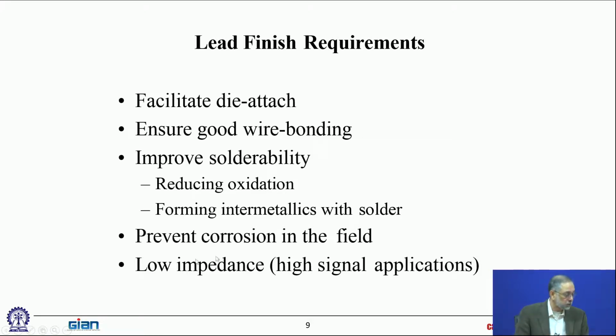And then again, not every pad will be soldered. The remaining will just have the lead finish on it. So that's supposed to also prevent corrosion in the field. So you pick the finish material based on that. And sometimes, in high frequency applications, the finish material has some electrical functionality also.